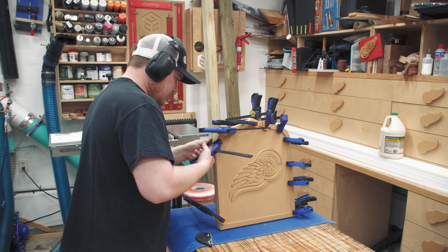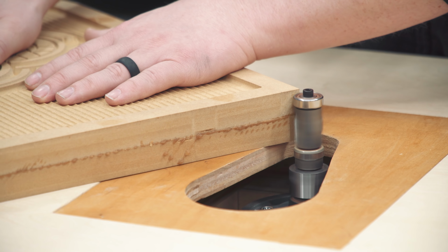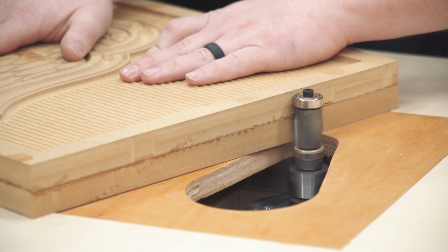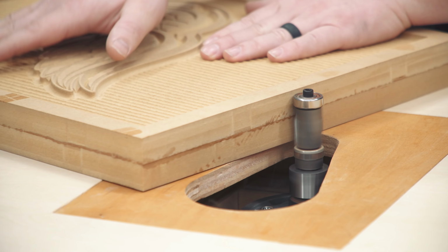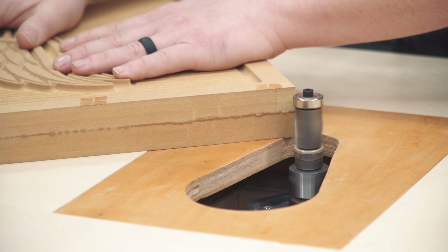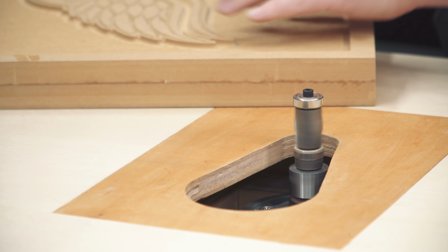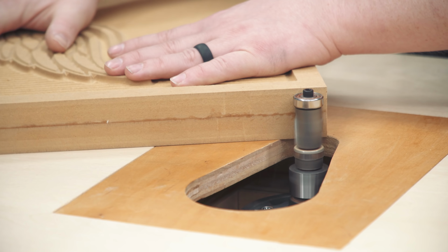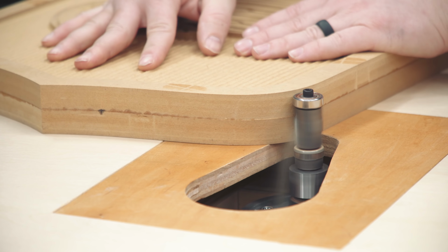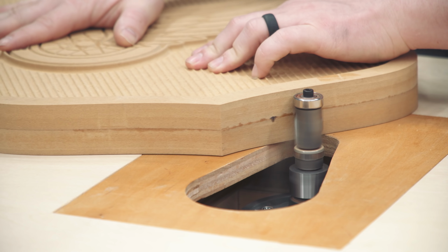Then the sign pieces are glued and clamped together, and the next day I ran the sign over the flush trim bit once again, but I had the bit height set so that the top bearing is guiding along the top piece of the MDF and made a pass all the way around the sign. Now this will even up half of any misalignment in the two pieces. And to get the other half, flip the sign over and make another pass all the way around, and that takes care of the other half of all of the misalignment. There wasn't much at all, but it just cleans it up nice and quick and easy, and the result is a smooth face all the way around the piece.